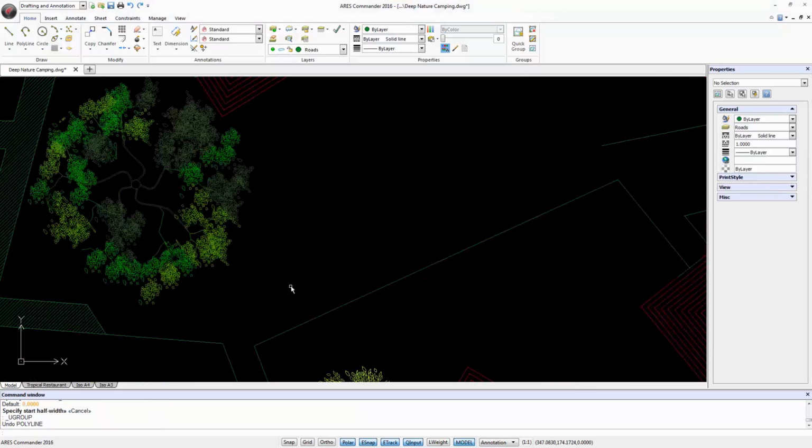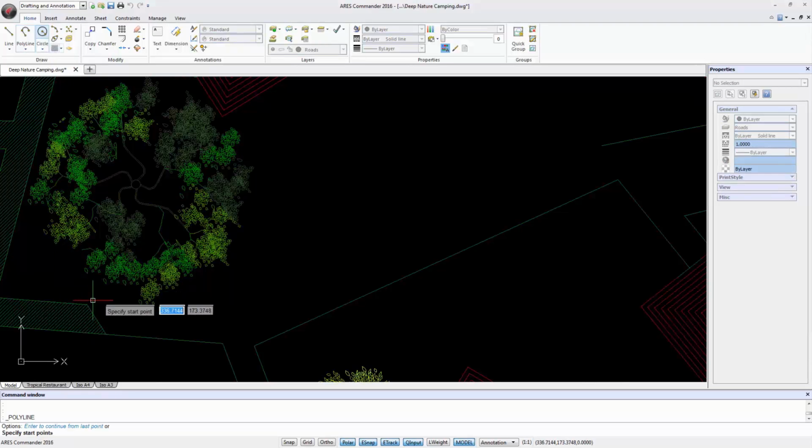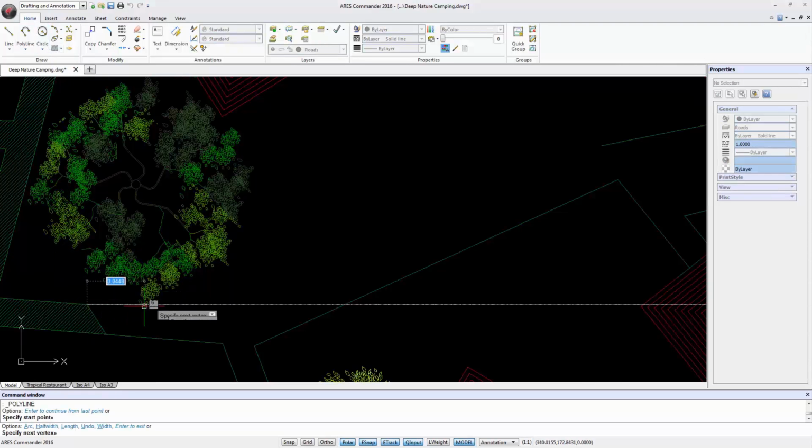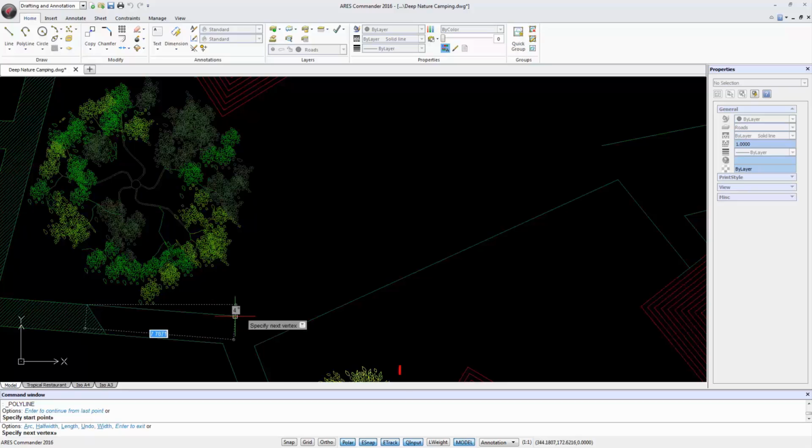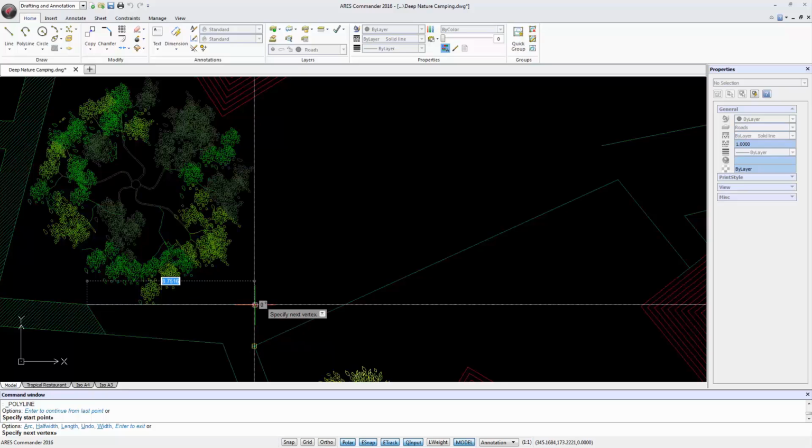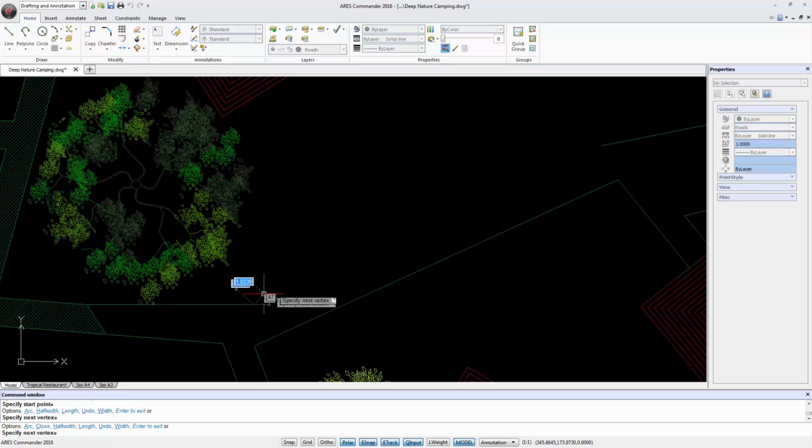But this is not all. We select polyline again and begin to draw a vertex. Thanks to the ETrack option, which is active, we can position the pointer for 1 second to get a reference point. Like that, we are able to achieve a tracking line until it meets the horizontal point from where we started. With a click, we are able to indicate that point.